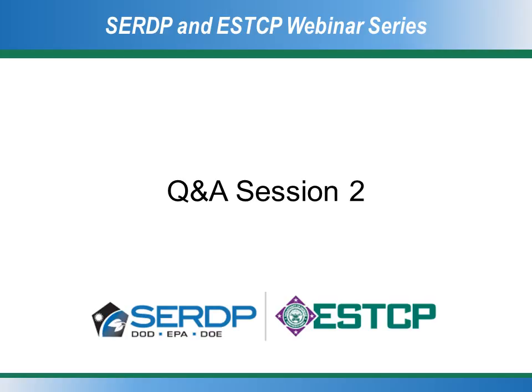Yeah, I would also add that if a contractor is making interpretations about concentrations of contaminants, that just cannot be the case. So I would just be wary about ERT images that show too much structure. Is there really a valid reason to show that much structure? I hope now you have an understanding that these images produce a limited resolution. So when you start seeing very sharp features, you really have to question whether that's from the data or not, or if they're just over-interpreting the data.